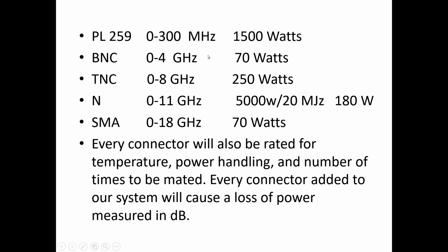I should have pointed out earlier, when you get to that skin effect, you have all of those electrons flowing into one area, creating a tremendous amount of heat. If you don't have the right connector, you can actually melt the material. And it's not unusual, particularly for a PL259 in the wrong frequency range, for the PL259 to melt to the SO239.